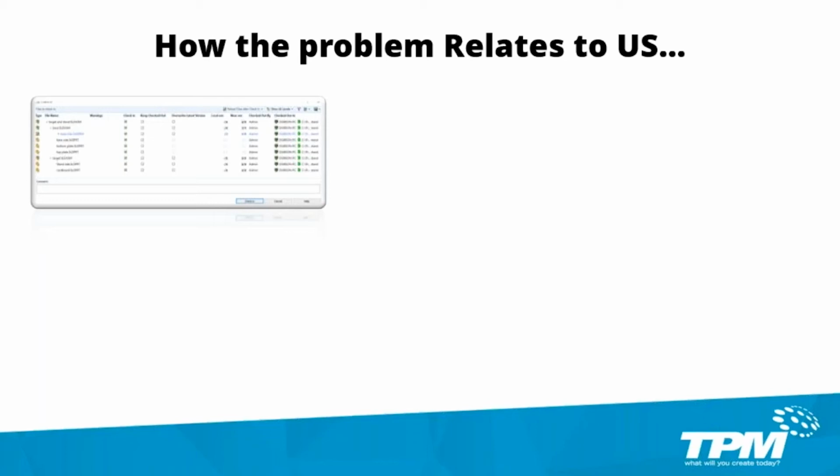The biggest impacts that we have when doing that type of operation, especially in a PDM environment, is when you get latest version of a lot of parts, when you check in a lot of parts, when you're checking out a lot of parts. Anything that we're doing those types of operations, we have to communicate to many different components.